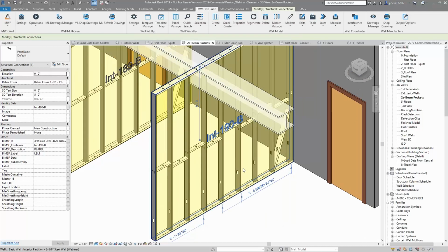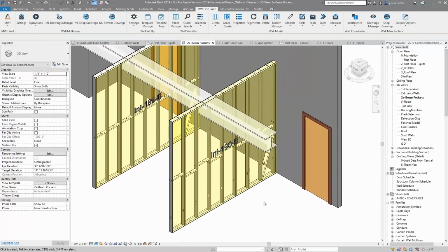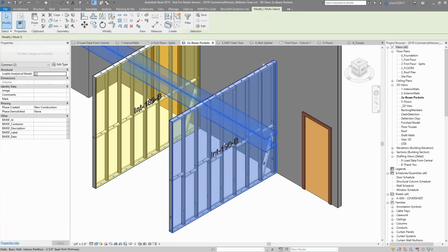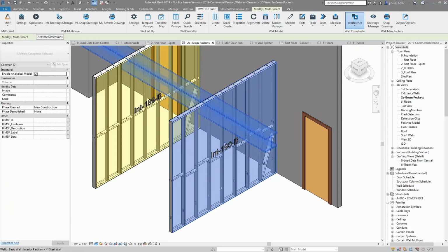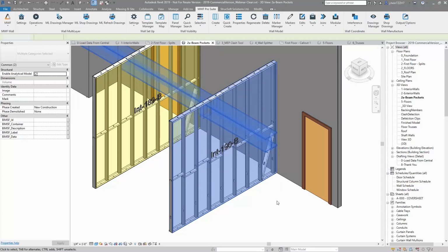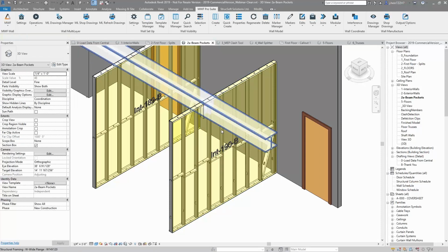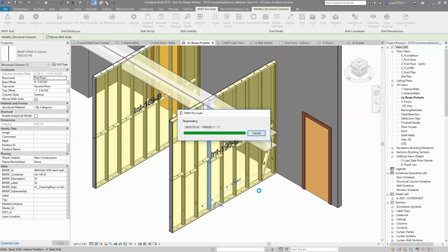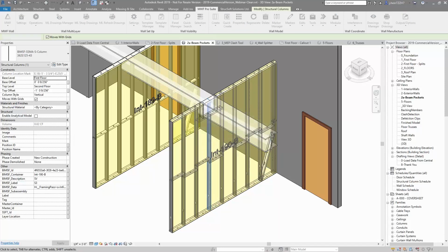The last part that we're going to use these panels for right now is we're going to create a beam pocket. So we're going to use our familiar Clash that we have, and we're going to create the clash between the beams, and we're now going to regenerate the panel. And our beam pocket should be up there because I already had it set by the markers.